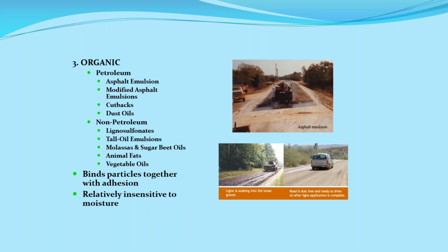But the lignin sulfate is a very good glue for a gravel roadway or unpaved roadway. The only problem is if you use just straight lignin sulfate, you've got to mix it in with your gravel. Have some water in it, mix it in. I've got some pictures I'll show you a little bit later on of a lignin sulfate project where we mixed it in with the gravel road material, then laid the gravel road material out, compacted it back down, and it glued it back together. It gets really sticky.